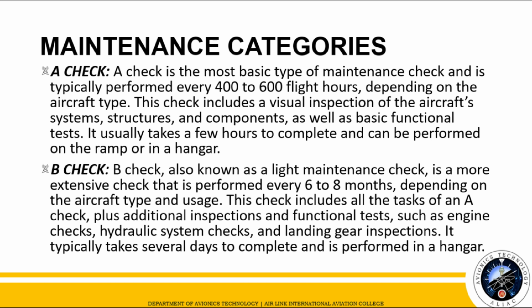In B check, every 750 flight hours, it includes A check plus selected operational checks, fluid servicing and lubrication, as well as an open inspection of the panels and cowlings. And the manpower need here is 200 man hours.